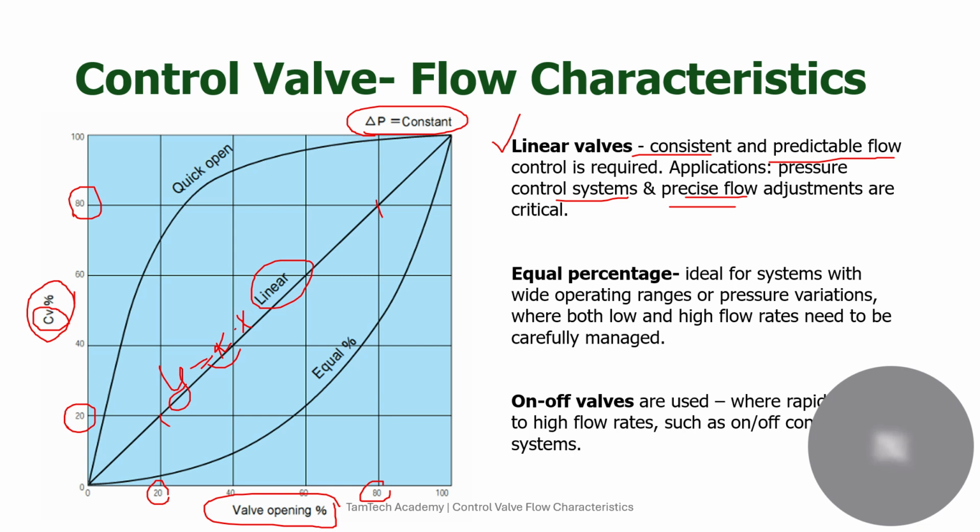Now let's continue with the equal percentage one. We say that a control valve is equal percentage when it has this shape. An equal increment of valve travel, like this, produces the same equivalent change in the CV at ideal conditions, as I mentioned before. To summarize, in an equal percentage valve, each increment in valve movement results in the same increase relative to the previous flow rate.